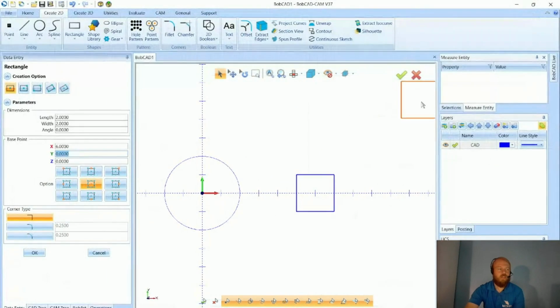You can turn that on and turn that off, and you can also type in those numbers. It starts off with 1/16 of an inch. You can change it. I'm going to change it to 1 inch, for example. And once I change it to 1 inch, you can see while I'm sketching, it's going to move over every 1 inch to sketch my drawing exactly where I want it. And if you turn off the snap increment option, you get more of a freehand option to sketch exactly where you want, and modify lines and arcs a lot easier without the snap increment setting.